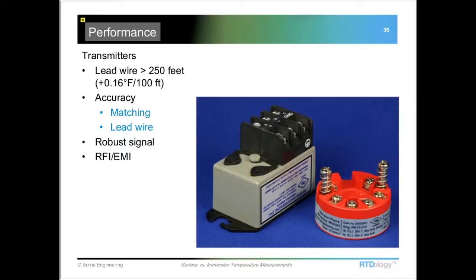We use that information to adjust the transmitter so that we eliminate a lot of the manufacturer's interchangeability out of that sensor, and we're looking at just its most basic performance, which would be short-term repeatability, a little bit of drift, and the self-heating, and maybe some other small errors.